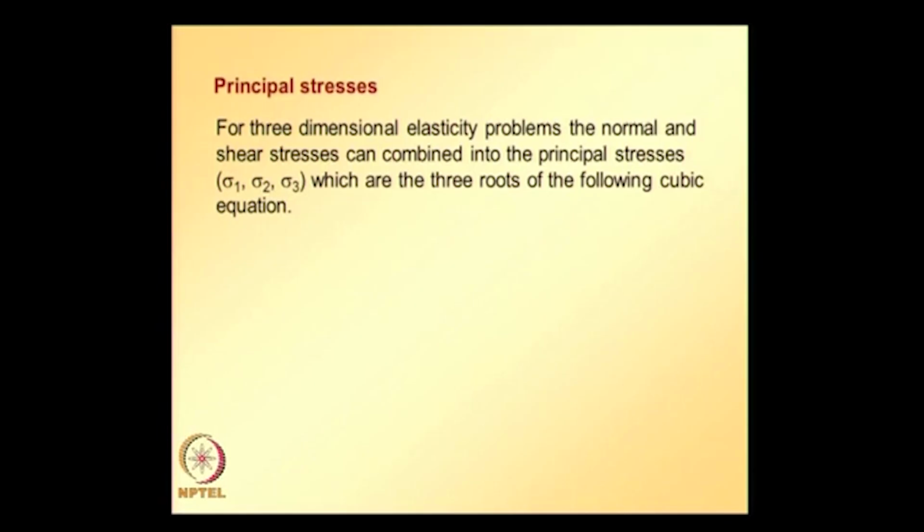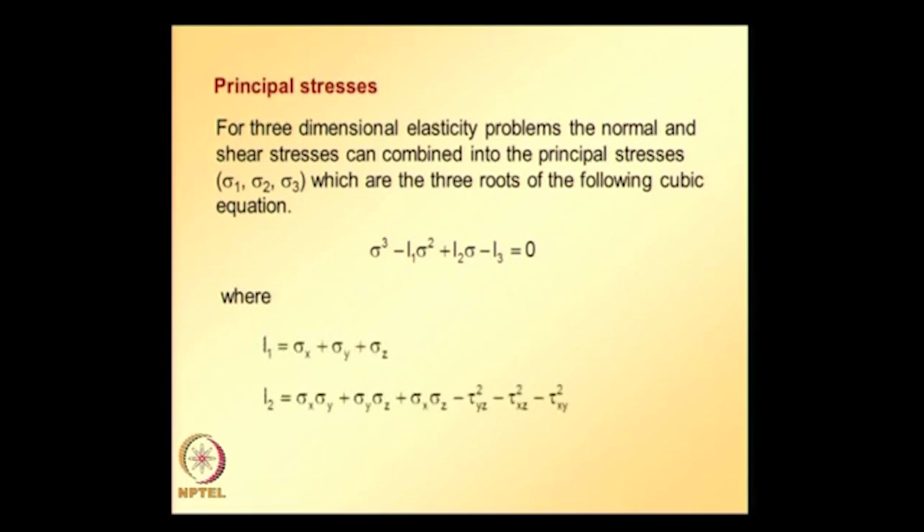So these principal stresses are going to be the roots of the following cubic equation, which is actually in terms of stress invariants. I1, I2, I3 are called stress invariants, where I1 is defined like this, I2, I3.